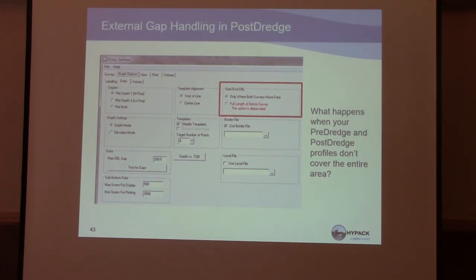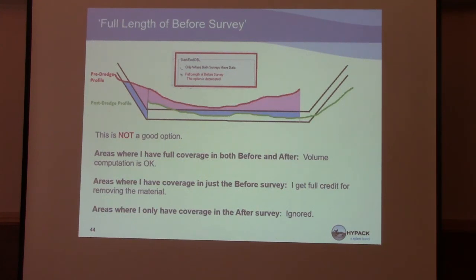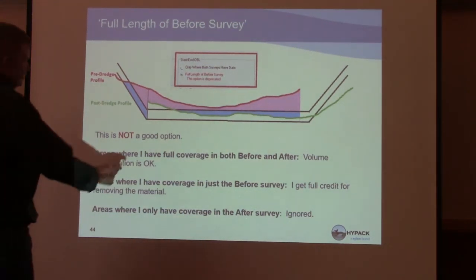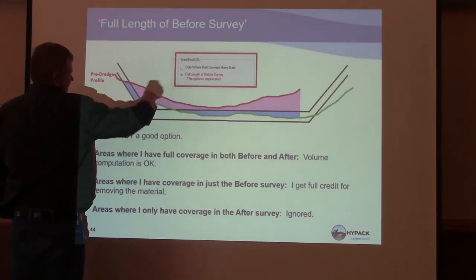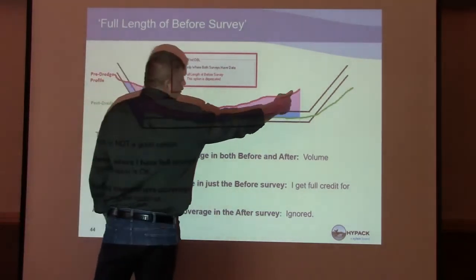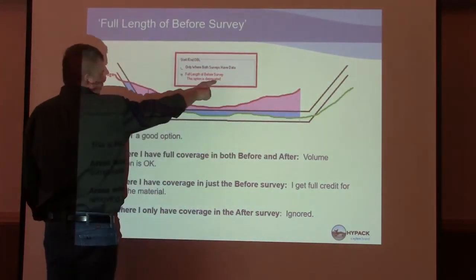What happens if you pre-dredged and don't cover the entire area? I always love when we have things that say this is not a good option at the start. This is not a good option. We have a couple spots within HYPACK where we did things that customers have asked us for, and to ease our conscience, we put in, make sure you know why you're checking this box. Similar to this one. This one says, I can only where both surveys have data. So if I leave that box checked, which is what I normally would do, I'm only calculating volumes up to there. Full length of before survey.